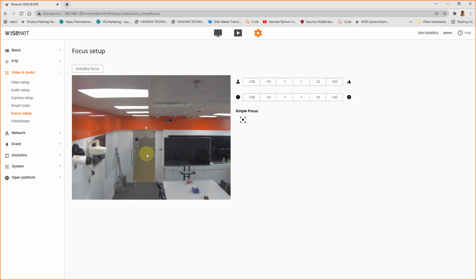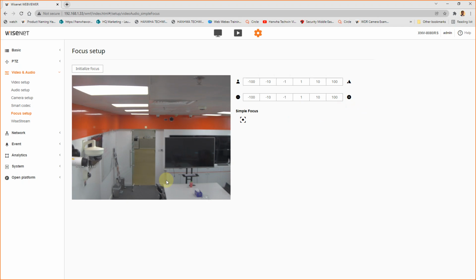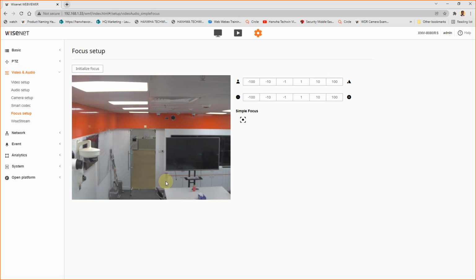Okay. Now, when I said privacy, door, all this is not a day-to-day requirement. I mean, in your public property, of course, you want to monitor all the areas, right? Waiting area, lift, lobby, storerooms, and everything. Only certain locations, entrances, you are interested in the door because you want to know who's coming in through the door with full detail, like a clear, more resolution you require for this area. Only for those locations you will actually zoom in. Otherwise, you will keep it as wide as possible.